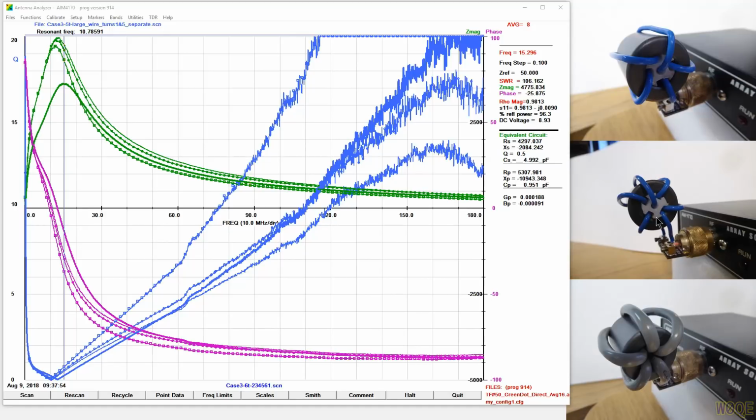So I built this little polyethylene insert that fit inside a core and could separate the turns and keep them spaced apart or not, or keep them together if they were in this slot, and any of the other four openings would keep them apart from the other turn, at least somewhat. I put 6 turns through here, and what's shown in this picture is the starting and stopping turns are adjacent to each other right here. But I could wind this differently. And the top 3 green curves here show the effect of that.